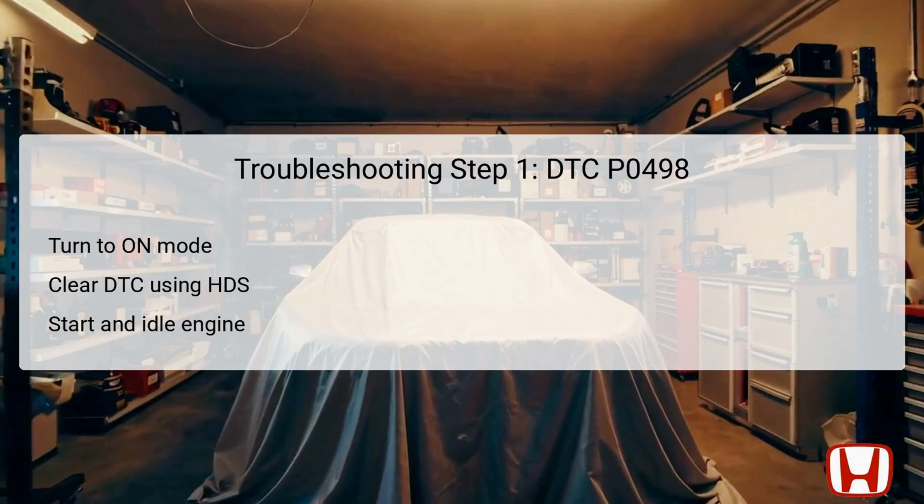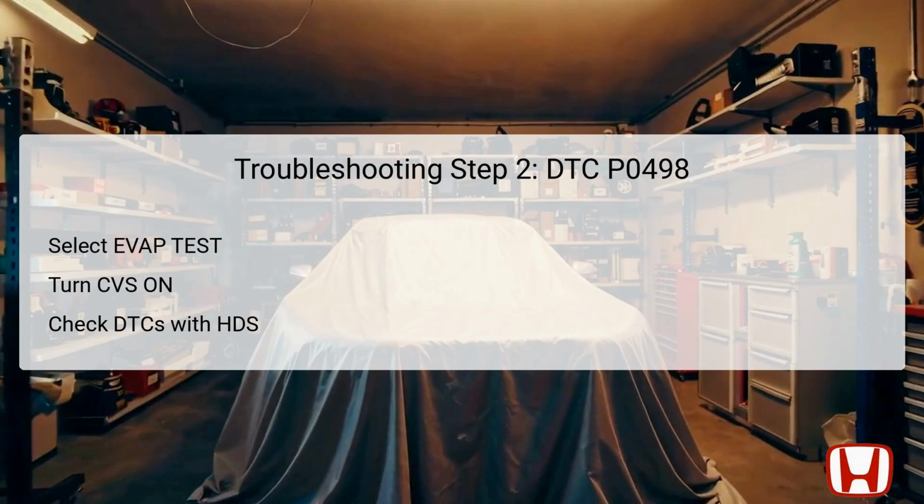deeper diagnosis if necessary. In troubleshooting step 2, the focus shifts to conducting an EVAP system test through the HDS. Access the EVAP test function and select the option for the single solenoid, CVS. This step sets the EVAP canister vent shut valve to the on position, simulating operational conditions. After performing this test, it is essential again to check for any pending or confirmed DTCs using the HDS.